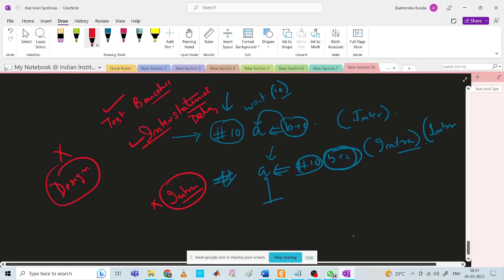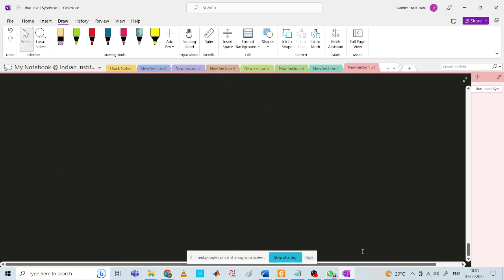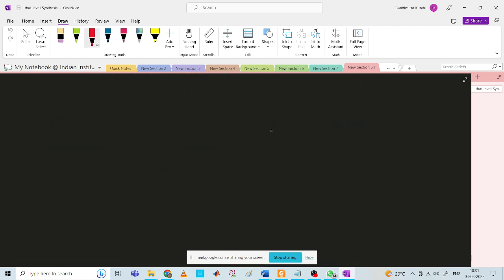See, in Verilog, let's say you want to have delays. Let's say you are generating a clock. The precision of this clock, what is meant by precision? Precision is the least amount of change that you can bring into your clock. This precision is 10 picoseconds.